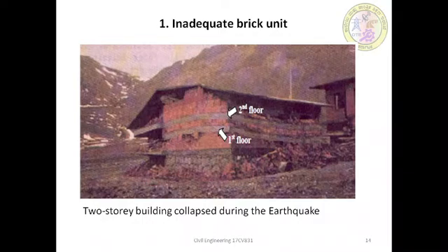Although their usage is improper in bearing wall applications, even such slight variations in the shape had some effect on the seismic damage observations. The observed heavy damage and collapse of buildings in earthquake regions are generally associated with hollow clay tiles used instead of solid brick units. In this figure, it shows the collapse of a two-story unreinforced masonry building in which a load-bearing wall with hollow clay tiles was cut laterally. That is the two floors, as you can see in the figure. They were crushed during the earthquake, and both stories collapsed.